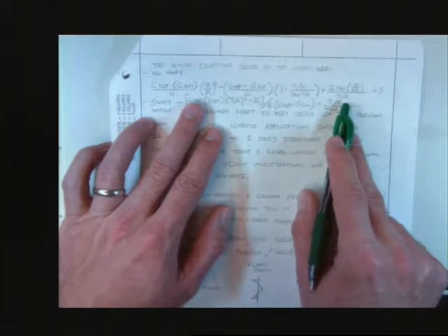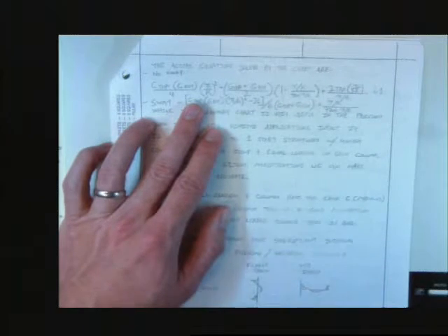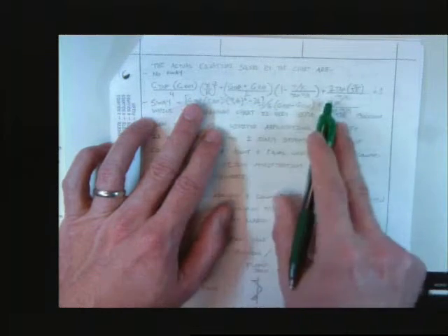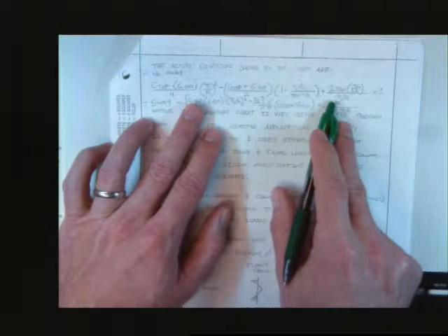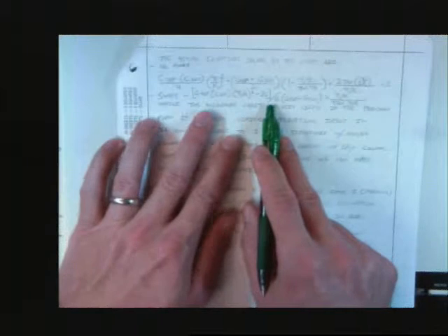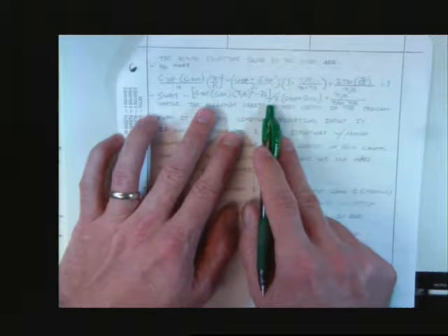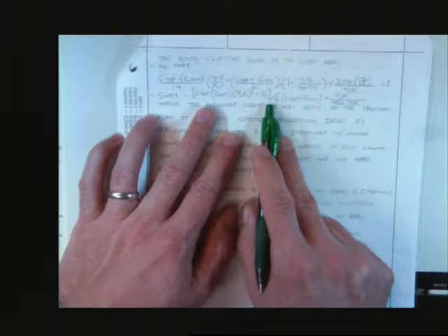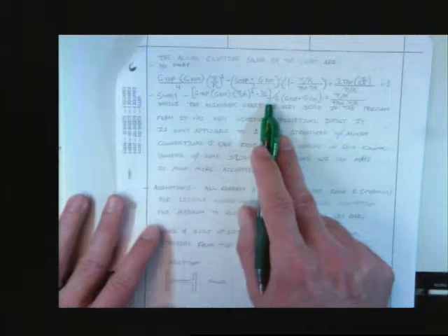Imagine having to solve for the K's. I mean, you can't even solve them. You can't even isolate them because they're basically in every single variable, and that's what the alignment chart does for you. Okay? It solves this equation for no sway, and it solves this equation for sway. You with me? Yes. It's pretty awesome.